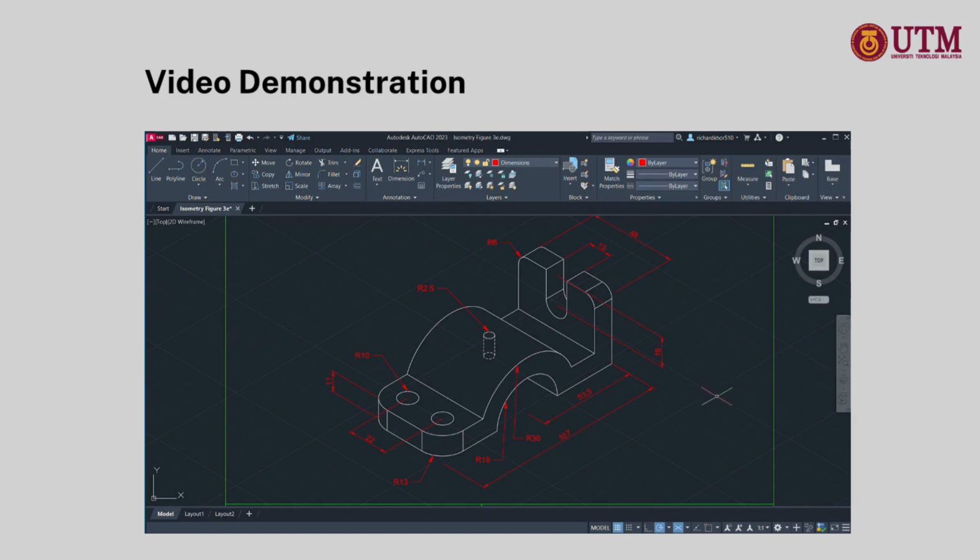Next we'll be moving on to nozzle size and position. The exact size and location must be shown to ensure correct installation. An analogy here would be this hole here. In case there is a nozzle, this nozzle should be drawn properly and all its dimensions should be placed properly as well. So this will be placed in the center and the dimensions should represent it clearly.